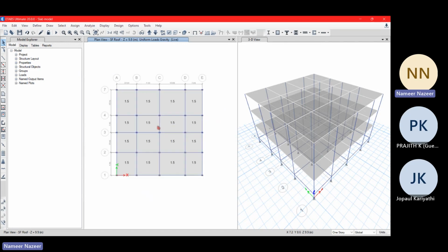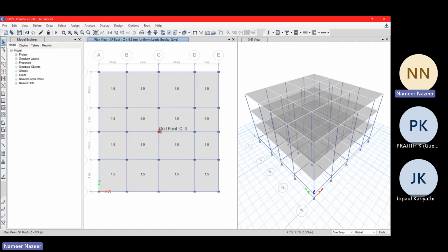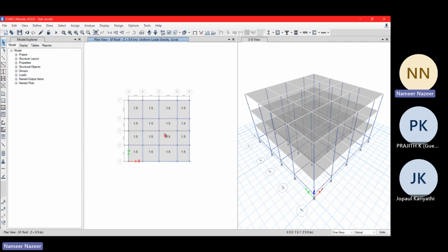Okay. Likewise, we can provide wind load, seismic load, and etc. So this is how we provide dead load and live load. These are the basic loads we can provide in this. Now, I need to provide a load combination. I need to combine these loads. There's a load combination, 1.5 dead load plus live load. That is 1.5 is the factor and dead load plus live load is the load combination.